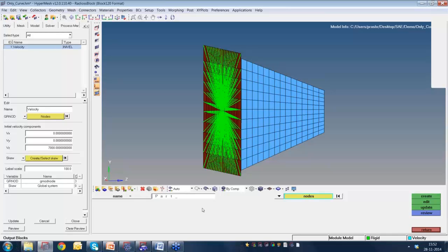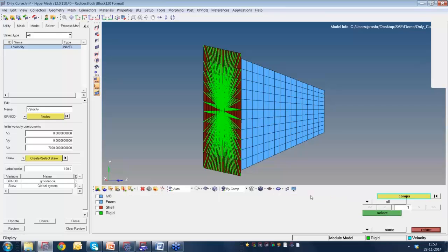First it is parts, and for that you have to bring it as components, and I'll select these two components, because when I show you the energy absorbed by the part, I have to see the energy on this part, so I have to request the output for that. So I'll click on components and select these two parts. You don't select the rigid, only these two are enough.